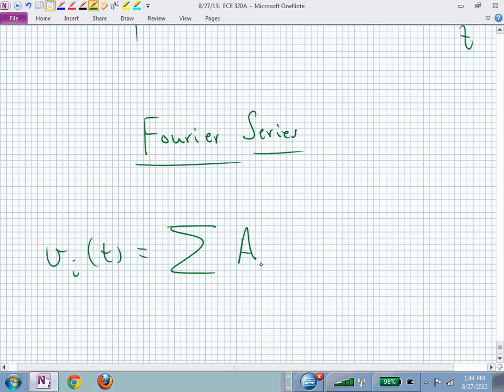Oh, that wasn't funny, huh? A sub n cosine of n omega naught t, let's say plus b sub n sine of n omega naught t, where we may let that n go from, oh, let's just go from 0 to infinity. So that when it's 0, we have our DC piece. We might want to pull that out, and then we have all these other pieces.